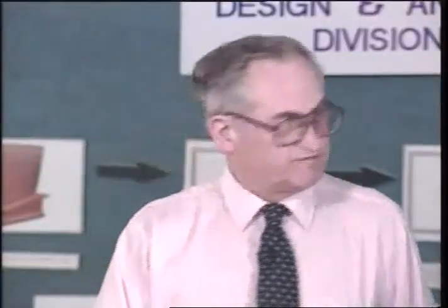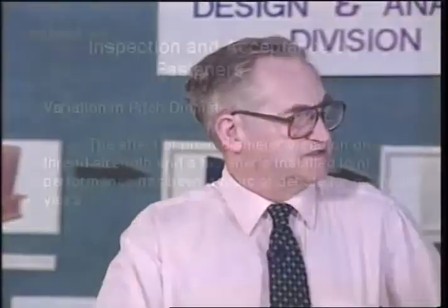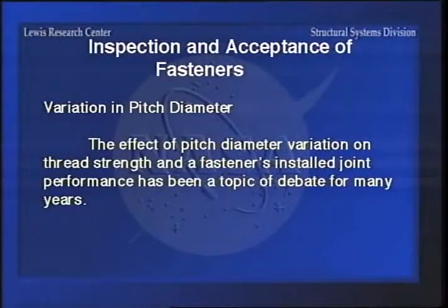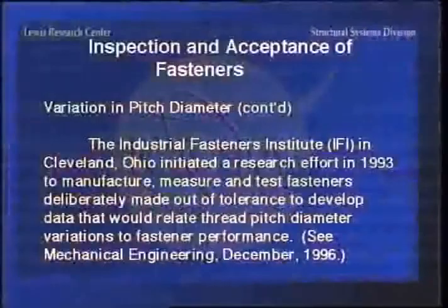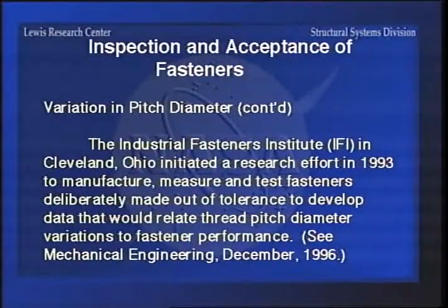Now, there have been various discussions through the years on how variation in pitch diameter on a fastener can do them in. And I guess this argument's been going on for 30 or 40 years. So the Industrial Fasteners Institute here in Cleveland initiated a research effort in 1993 to manufacture, measure, and test a bunch of fasteners that were deliberately made out of tolerance on pitch diameter just to see how bad it was.